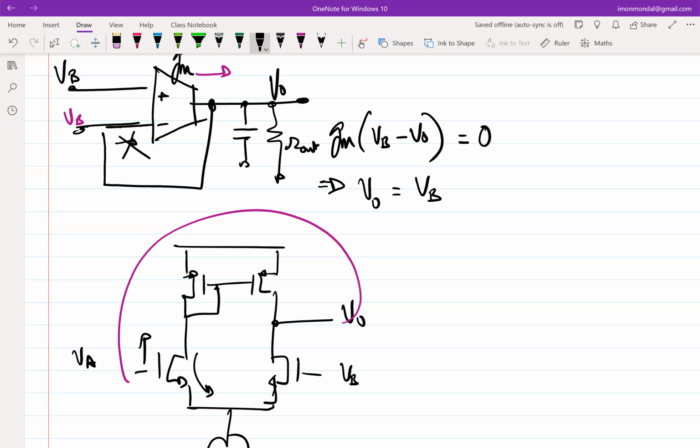This will increase. So this current is again mirrored, right? So this current is going into this node voltage. This is increased. The mirrored current is also increasing, right? So into the node voltage V0, will the node voltage V0 increase or decrease? It will increase, right? Current is getting driven into V0, it's going to increase. So naturally, this is positive feedback because that voltage is again getting fed back. So that is not the case. Then obviously the only other solution is this.